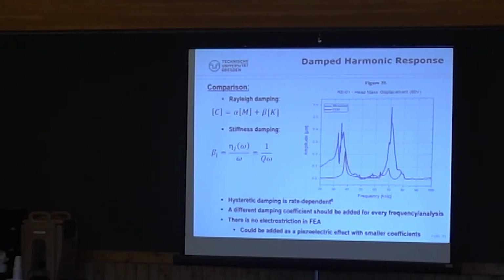But actually, I do change the damping. I actually superpose two simulations. So I do one simulation with hysteretic damping with this value for the beta at the first frequency of resonance, and the second simulation for higher frequencies I would do with a damping with the second resonance frequency.